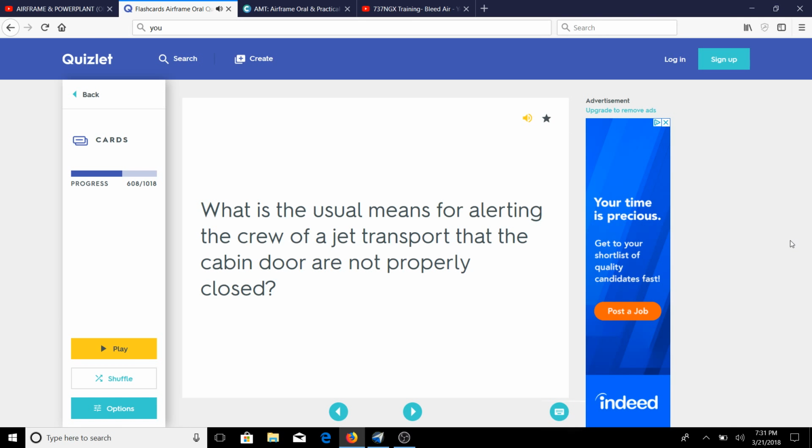What operating parameter is indicated by a tachometer? Engine RPM. What is the name of the effect that causes a gyro to respond to an applied force at a point 90 degrees further in the direction of rotation? Gyroscopic precession. What are the three sources of power used to drive a gyroscopic turn indicator? Air from a vacuum or pressure source or an electric motor.